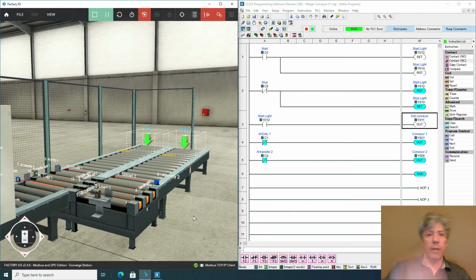So I'm going to go ahead and tackle this. Let's just reset this simulator, because I don't really want to see any pallets there right now, and think about what I want to do, because there's really a whole process of moving conveyors through this system. For example, let's just say that I want conveyor 2 to move the pallet from the load position. Let's just say somehow we get it into the transfer conveyor. I want it to move it from there, move it over and bring it out of the system.